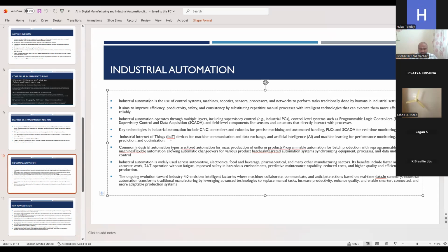But suddenly, if you want to know what happened if it is crossing 10,000 kilowatt hours and going to 12,000 kilowatt hours for the same output, we can fetch from the energy management system, the IoT system, which particular machine or which particular operation has cost the higher energy. And there we can work on it, so that it will be useful for reduction of energy consumption also.